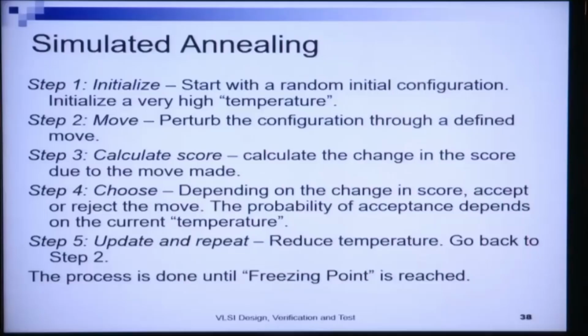Now from that initial configuration, I make moves over the state space. At each move, as I said, I either merge or split. With that merge or split, where do I go? I go to another merging of the temporary registers and operations to obtain a different allocation of the functional units and registers, and we will have an associated mux and demux cost. And due to that move from one state to another, in the current new state I will have another cost of the solution.